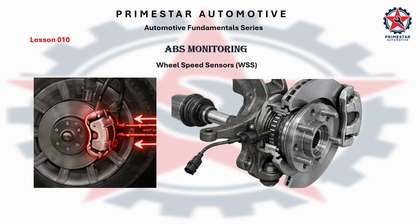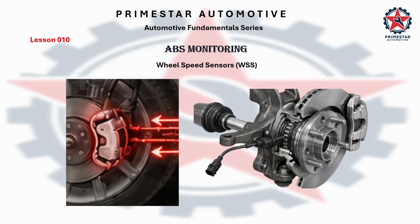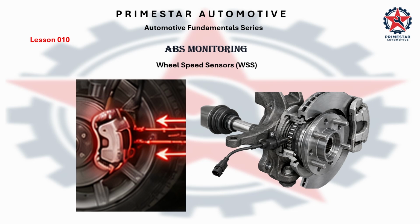The wheel speed sensor monitors the rotational speed of each wheel and sends this information to the ABS/ESC control module. By comparing wheel speeds, the control module can detect if a wheel is beginning to lock, slip, or spin, allowing it to adjust brake pressure and help maintain traction, steering control, and vehicle stability.